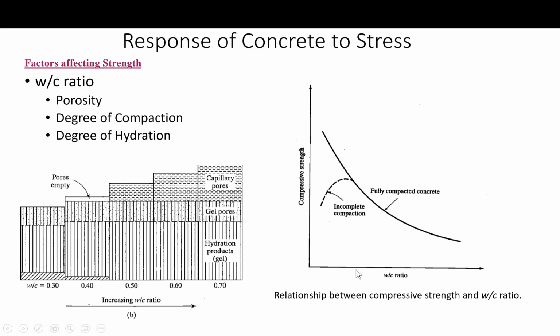As we decrease the water cement ratio below this point, if the concrete is not sufficiently compacted, reducing the water cement ratio will not help much beyond a certain point. Okay, so fully compacted concrete is fine, but if the concrete is not sufficiently compacted, lowering the water cement ratio will not help, as you can see. All right, keep that in mind.